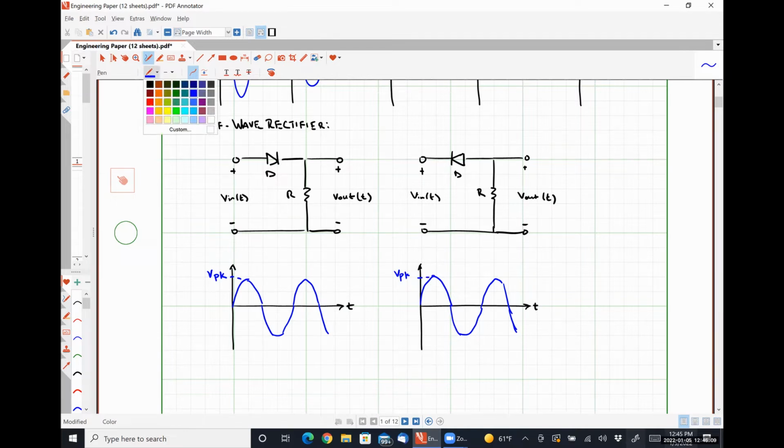All right, so for our left-hand half wave rectifier, our output signal using the constant voltage drop diode model should look something like this. So effectively, our diode doesn't turn on until V_in is larger than V_D on, at which point our output signal begins to follow the input signal, but there's always going to be that little discrepancy.